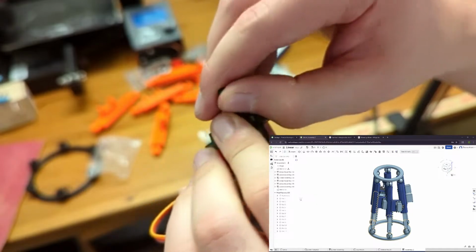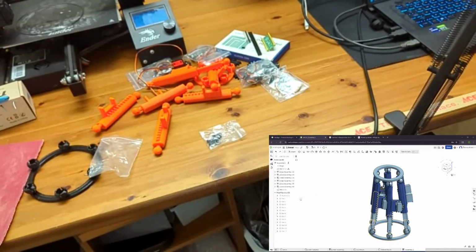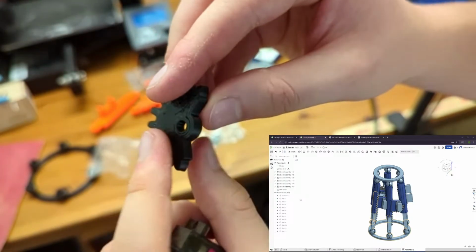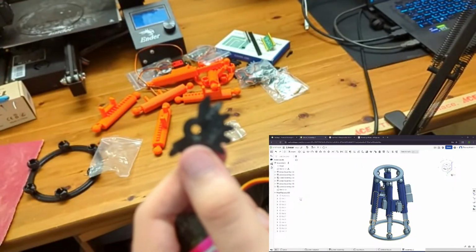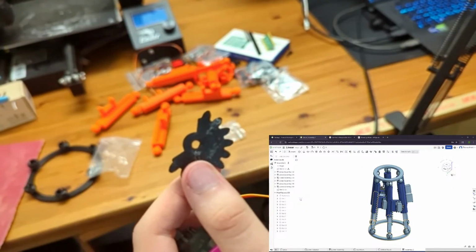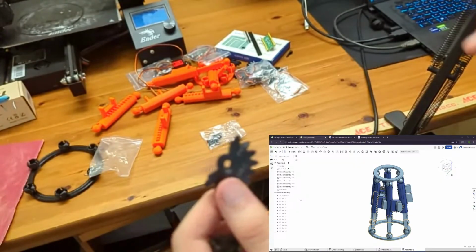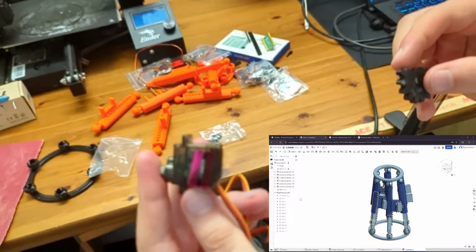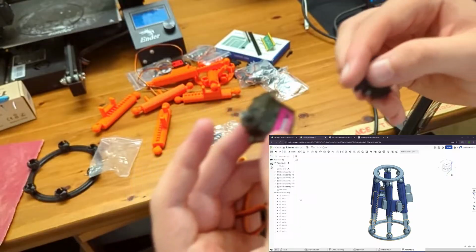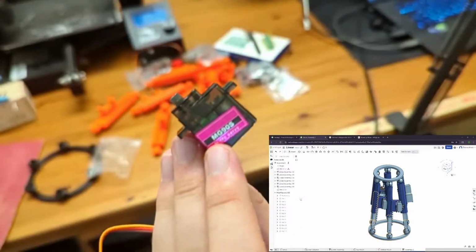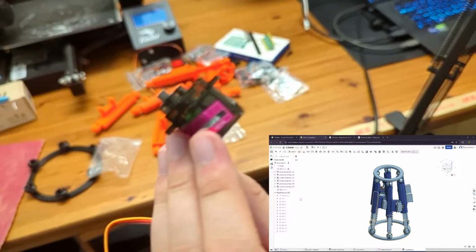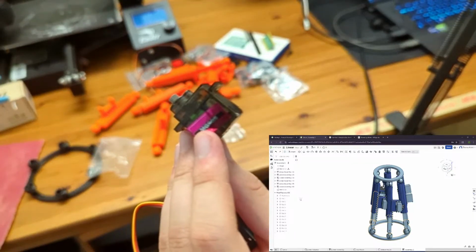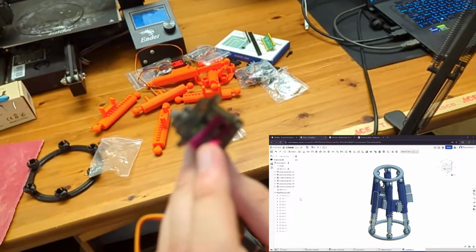So what we're going to do instead is I actually just printed this hole a little bit too small out of some PETG filament, and then I'm just going to do a press fit, which will basically carve those splines right into the gear. It's not perfect. With a servo any stronger than this, it would strip out pretty quick. But because these servos are so small and very low torque overall, the servo actually stalls well before the plastic strips off of that. So I think this will be just fine. I've used it in the past without any issue.